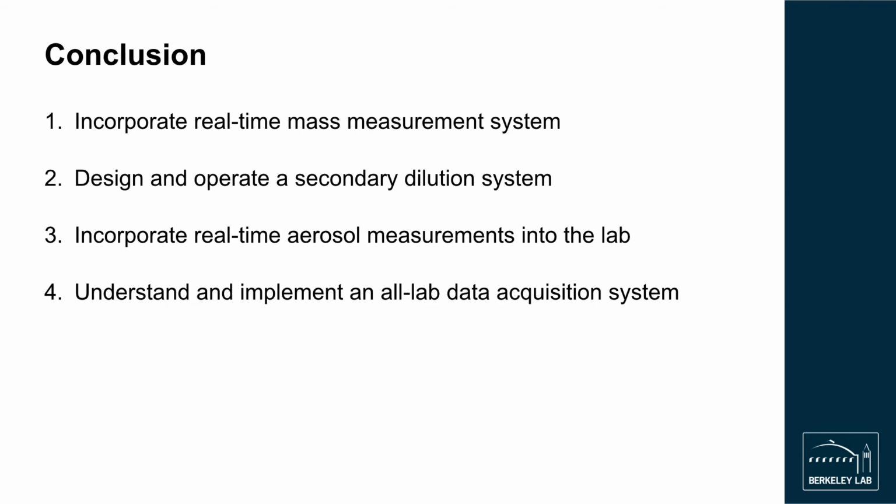However, if your lab is interested in the design of next-generation cookstoves or research into the fundamental mechanisms driving cookstove emissions and health impacts, a more advanced laboratory design may be necessary. To achieve the goals of your advanced lab, we hope that you consider incorporating a real-time fuel and water mass measurement system, designing and operating a secondary dilution system for aerosols, and incorporating a real-time aerosol measurement system into your lab. Finally, we hope you understand the benefits of and implement an all-lab data acquisition system.